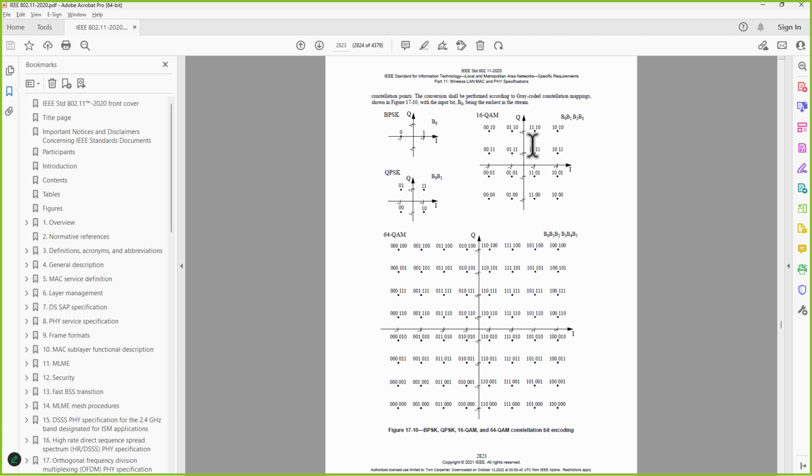But basically, we can see then that we've got 4 bits per symbol. And so we're going to modulate the same waveform for the symbol period, and then keep it the same if in the next symbol period we want the same 4 bits, but change it if we want a different 4 bits. Now, no matter what string of bits, you might have 1,000 ones and zeros in a row. No matter what string of bits, some combination of all of these different 4-bit values can be used to represent that 1,000-bit string of ones and zeros.